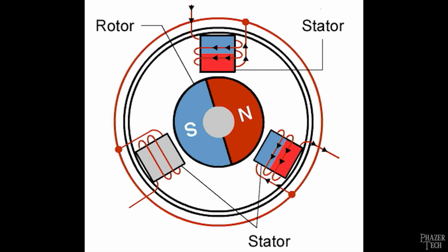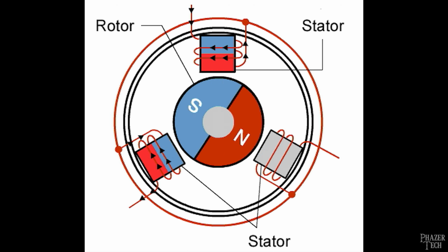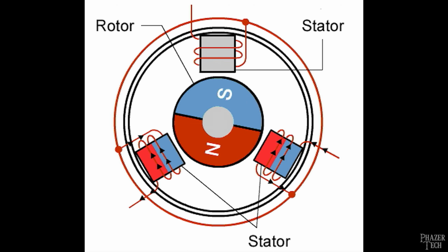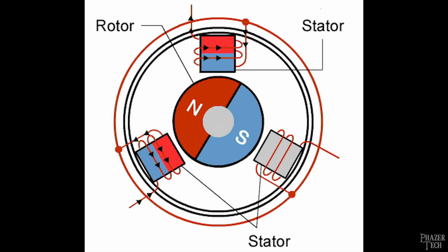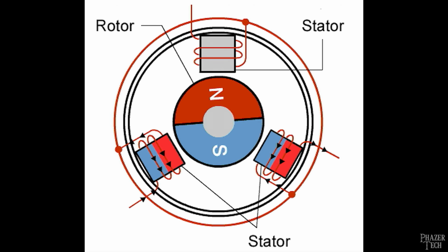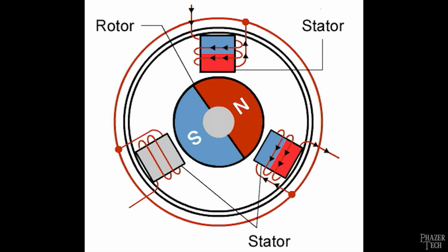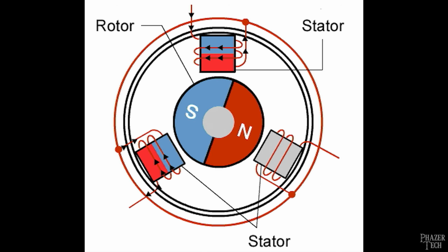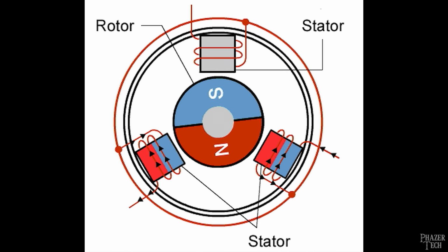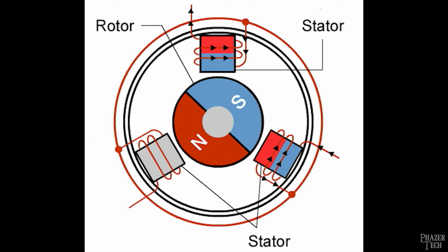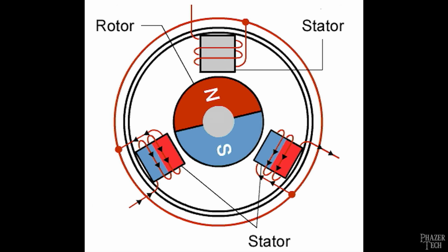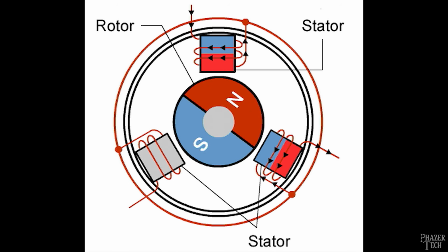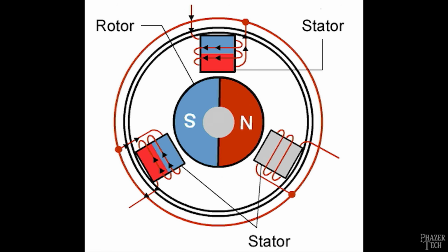As their name implies, brushless motors don't contain a brush and are typically configured like you see here. Now the permanent magnets are directly attached to the rotor, and the coils are attached to the outer frame, which is referred to as the stator. The coils are energized in such a way that they're constantly switching polarity back and forth, but they do so at slightly different times from each other, in order to keep the rotor moving at a continuous rate.